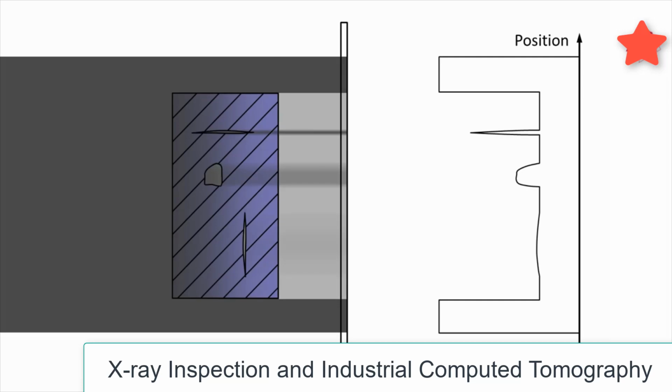Defects such as cracks or pores absorb very little radiation. Therefore, places with defects lead to higher radiation intensity at the image capture unit than flawless places. Defects extended in beam propagation direction can be seen particularly well. Those defects which only have a small spatial extension in beam propagation direction can hardly be seen, or cannot be seen at all.